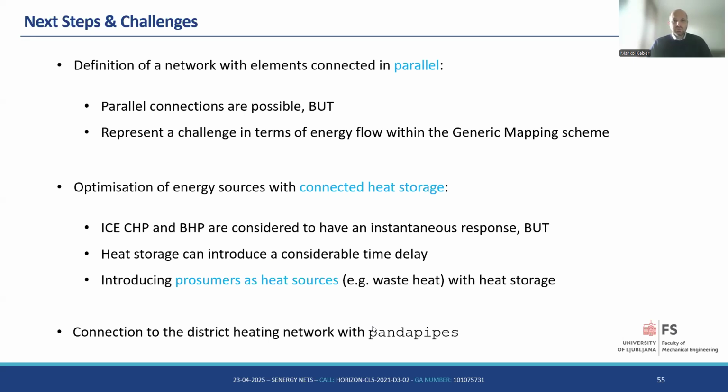We're also looking at heat storage. So what can we do with heat storage? Heat storage is an element that introduces a time delay, whereas the CHP and the booster heat pump are considered to have an instantaneous response. The time delay will obviously bring some complication to the whole analysis. But we're not worried about that, because we believe that by also introducing prosumers as heat sources, and heat storage, we can optimize this system in a much better way.